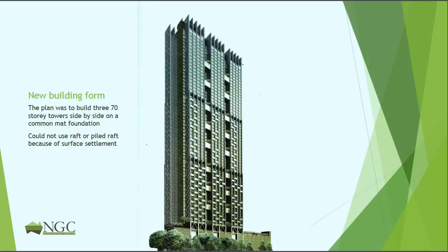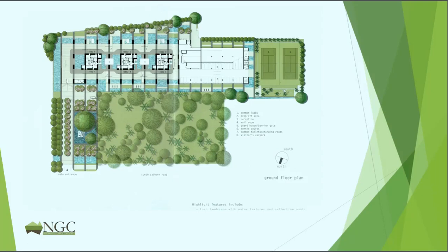The second project I want to talk about is another job in Bangkok, but this time for a rather higher structure, 3 70-story high, over 200-meter high towers sitting side by side on a common foundation. It's not a raft foundation. In Bangkok, the surface soils are too soft to allow you to use an actual ground-bearing raft foundation, so it's a piled mat foundation. There are actually 399 piles under that main structure.